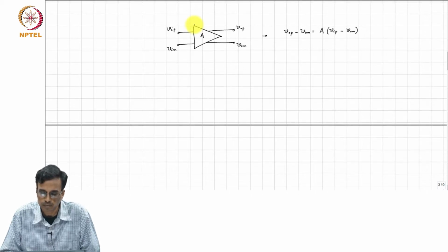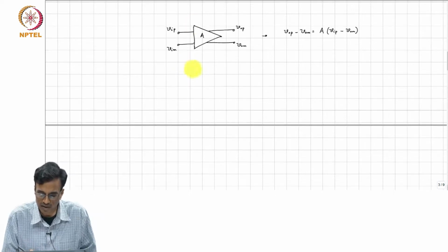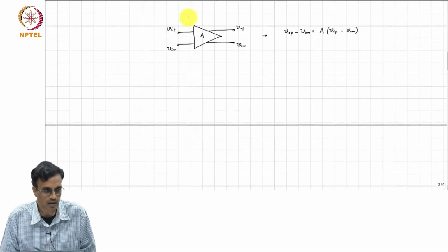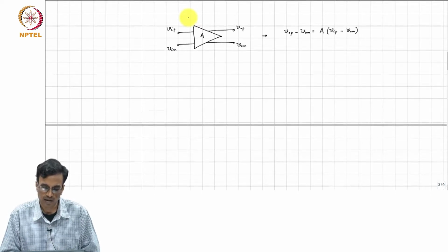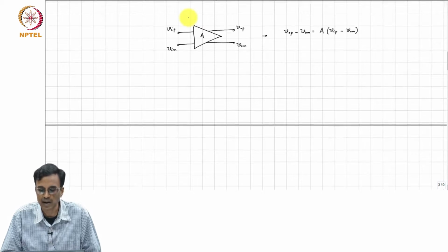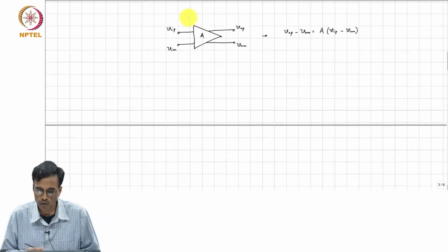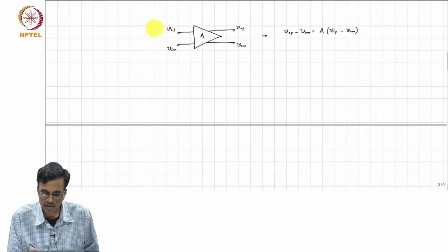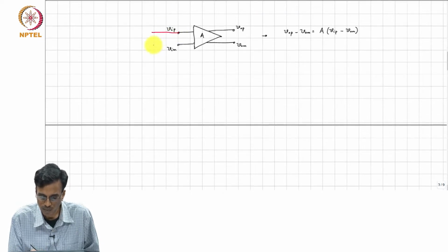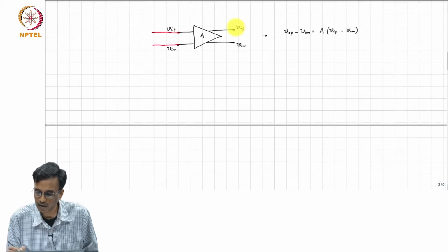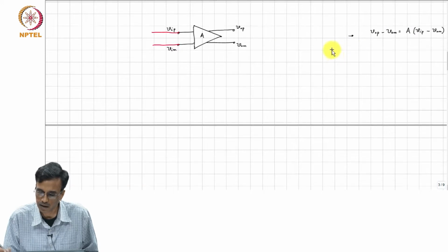In this scenario, we still have, I mean, the amplifier will still have input referred offset and flicker noise, and that still causes problems. However, fully differential operation makes it very easy for us to implement chopping with a slight difference in the chopping waveform, and that is the following.